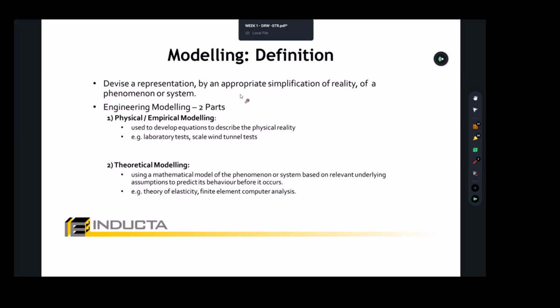By the way, the hand calculations you're going to be doing in your assignment 1, which we started last week, are static. We're going to use the static methods. You can't do dynamic; you can't do a 10-story building dynamically. You will see that it's undoable. We use static principles to work out the earthquake stresses.